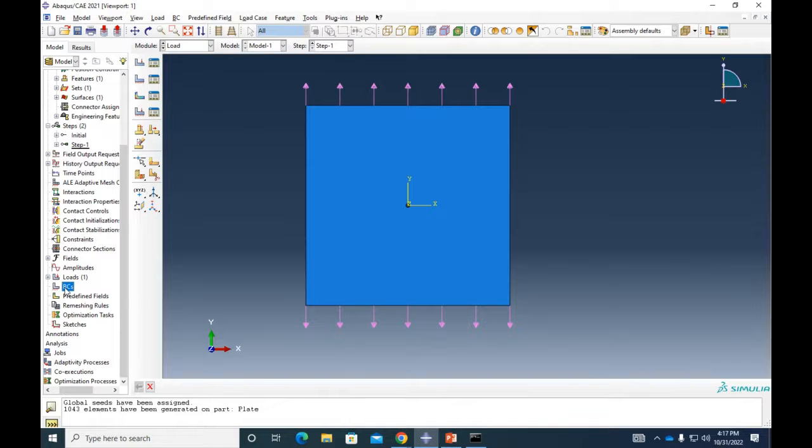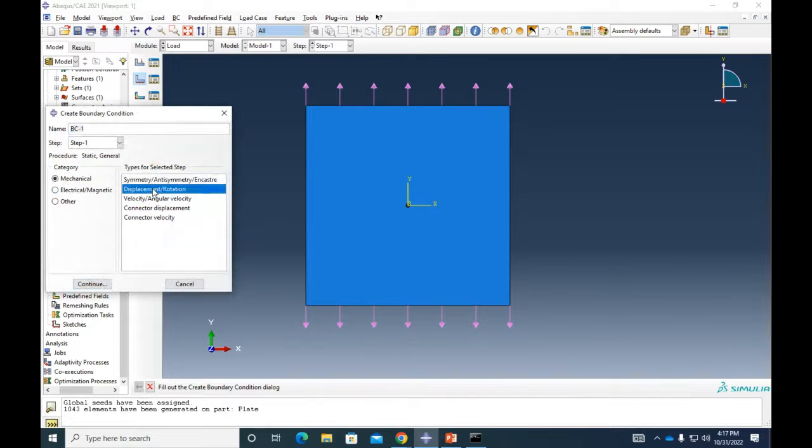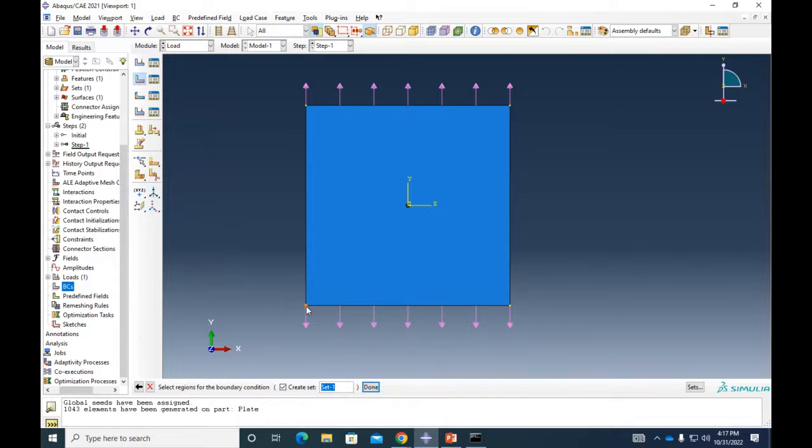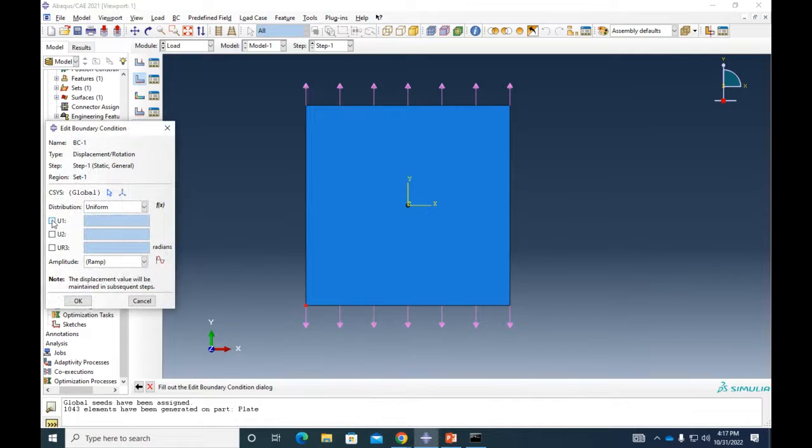So what I always do is that I select this point in here. I always select the bottom left corner. And then I say, hey, that particular point cannot move in X. Because imagine, this becomes very unstable. So we apply this load, but it could be here or here. We don't say anything about X.